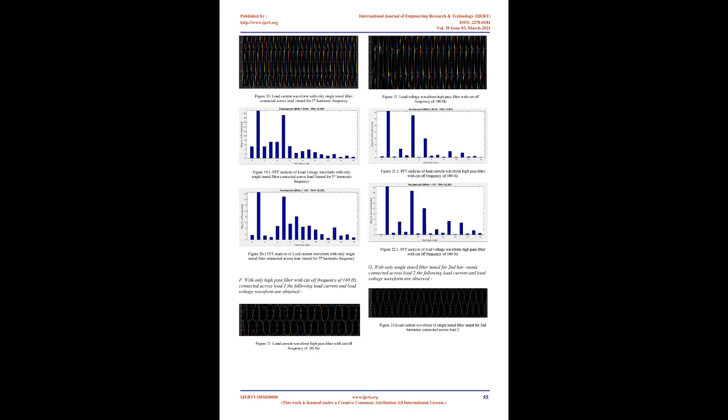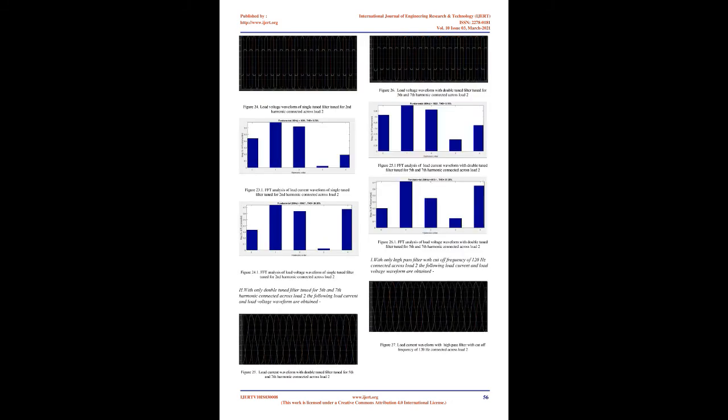The passive power filters are Simulink, a registered trademark, models named passive harmonic filter. They are configurable as single-tuned, double-tuned, and as a high-pass filter. When the currents on the three live wires of a three-phase system are not equal or are not at an exact 120 degree phase angle, the power loss is greater than for a perfectly balanced system. The method of symmetrical components is used to analyze unbalanced systems.